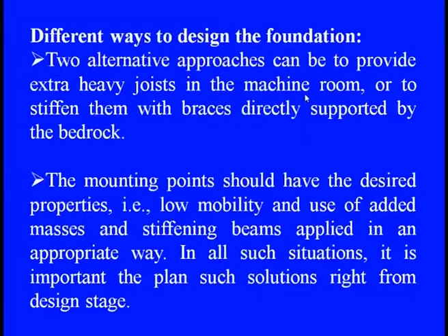First, provide extra heavy joists in the machine room, so that it will provide strong support. Or, if we cannot provide this because of space, then we can stiffen those foundations with braces which are directly supported by the bedrock.